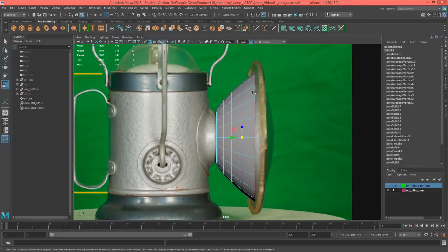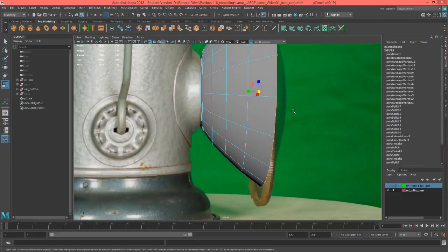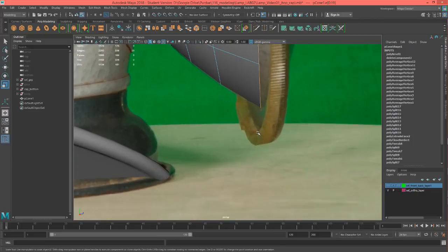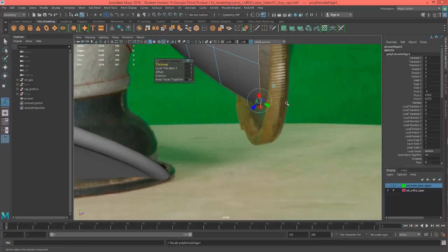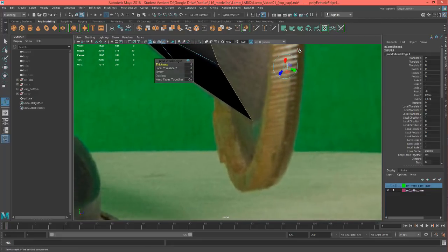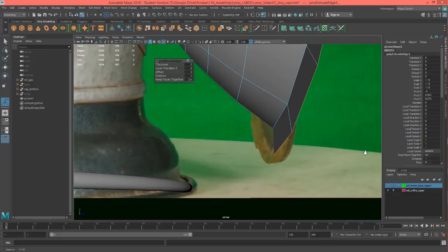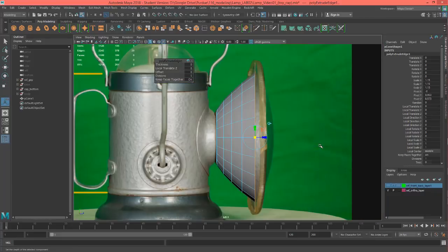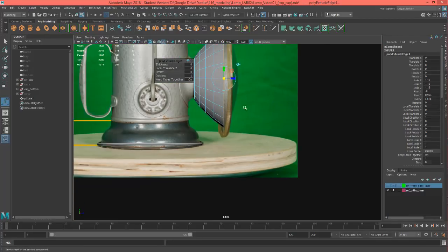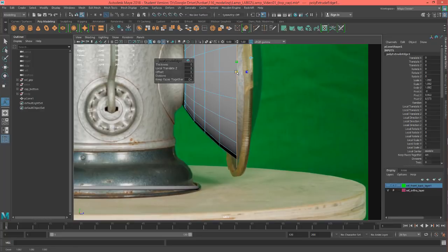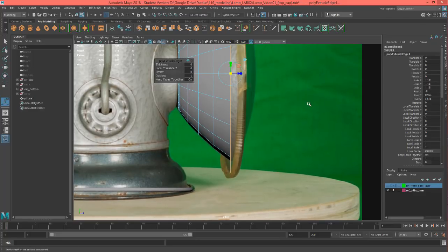there we go. Okay, so now I'm going to take this open edge here and go to my perspective view, and I'm going to actually scale it, or I should say extrude it so that it comes down to about right there. So I'll just go ahead and hit extrude again. Okay, and what I want to do actually is I'm going to do the scale trick again. So just click on that and then scale it out. It'll go straight from the center. And let's just be precise. So it needs to come just a little bit back. About right there. Okay.